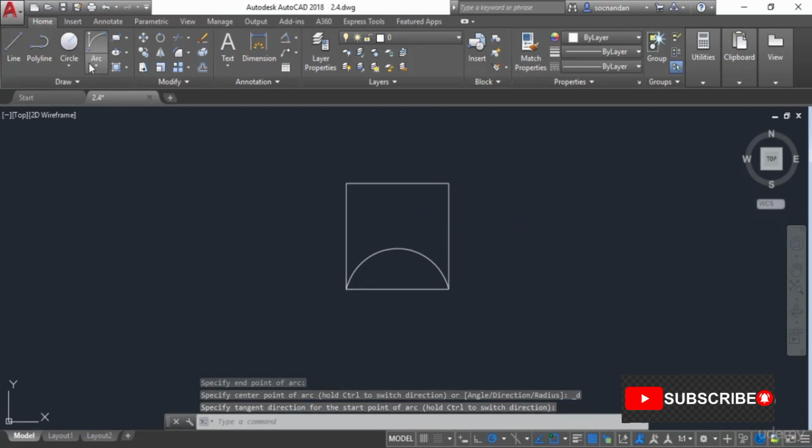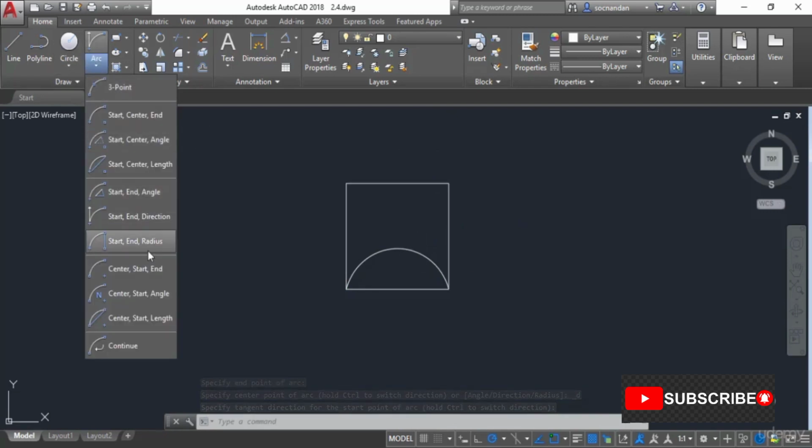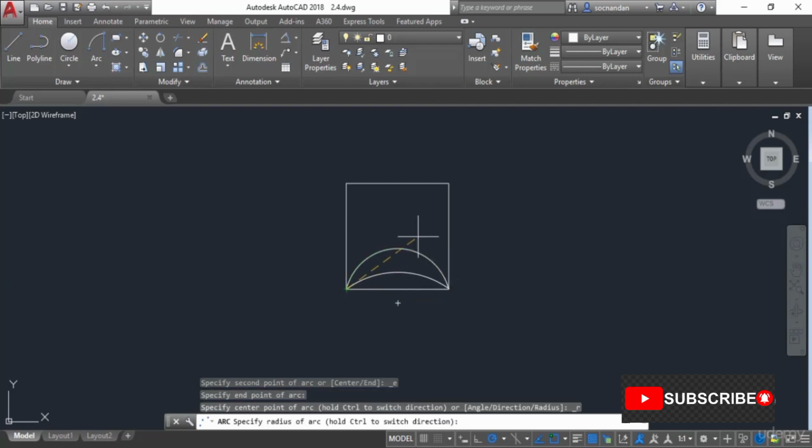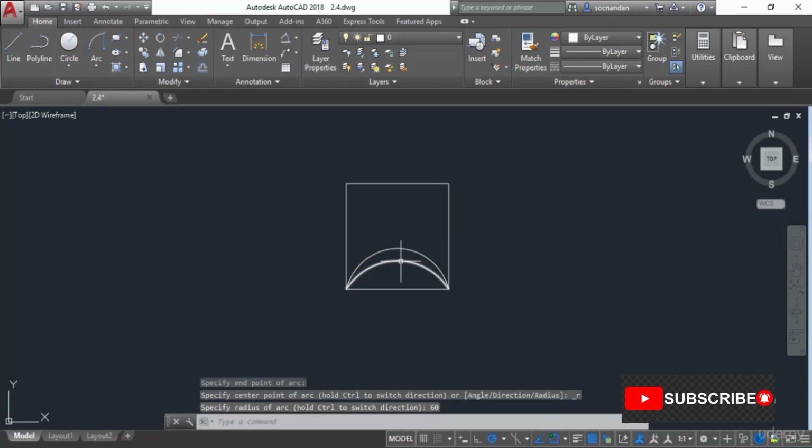Now let's look at the other option, which is start and radius. In this case, we need to first click at the start point, then we need to click at the end point, and now we need to specify the radius value. That will be the radius of the arc. So let's type a radius value of 60 units, and here we have it. Now this arc has a radius of 60 units.